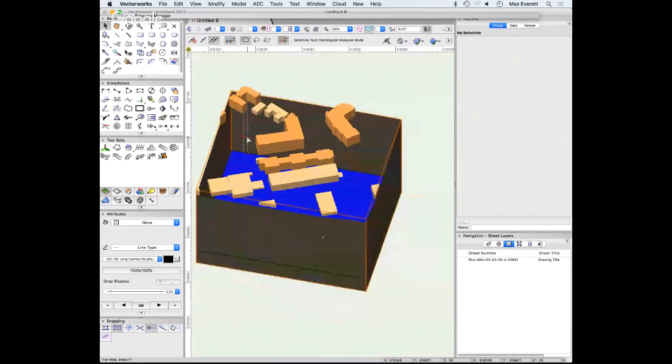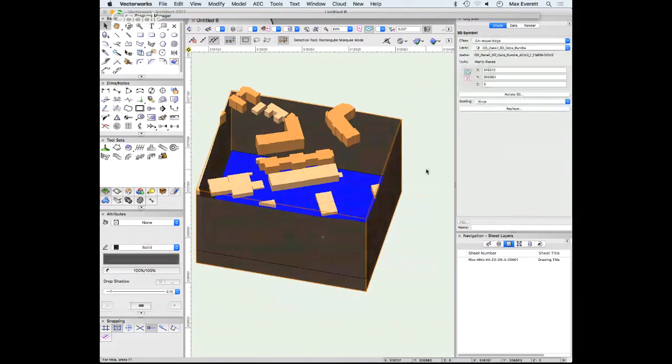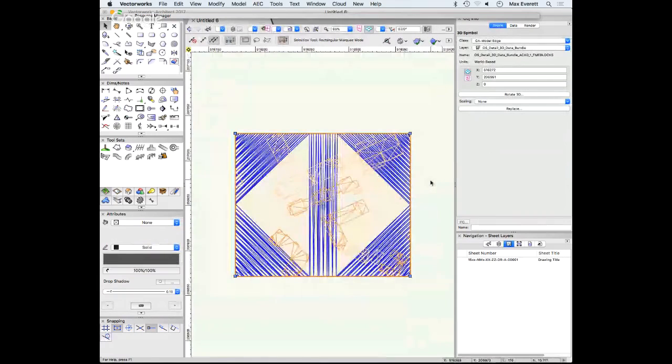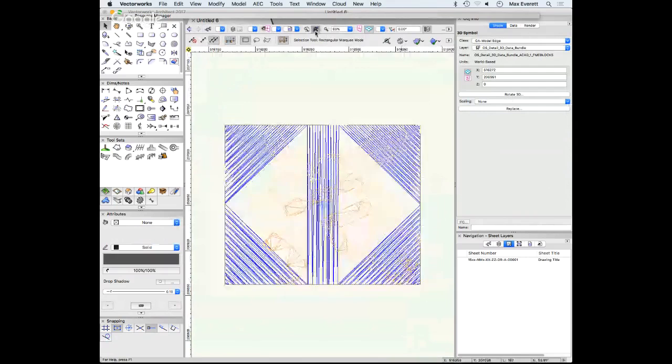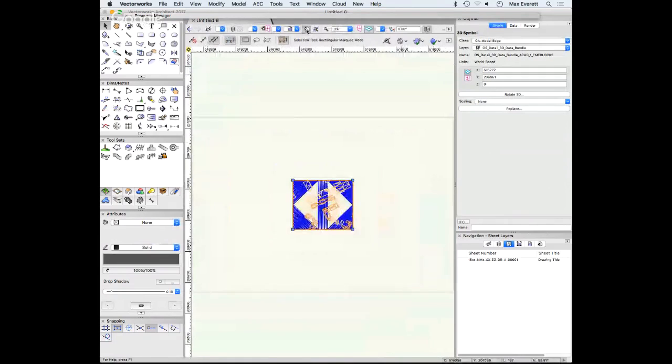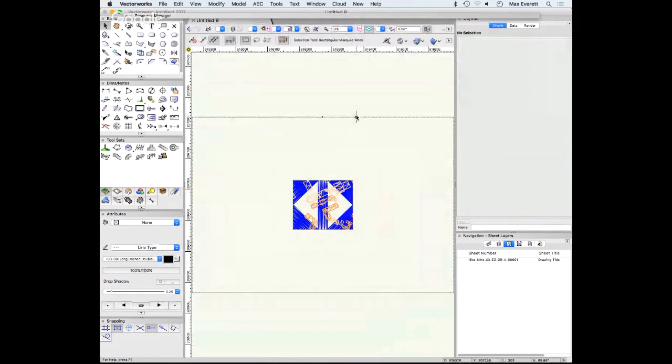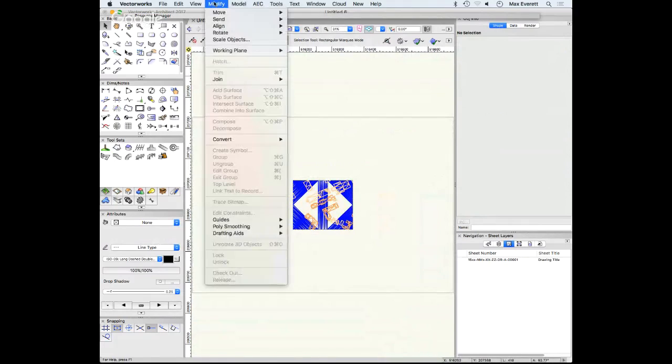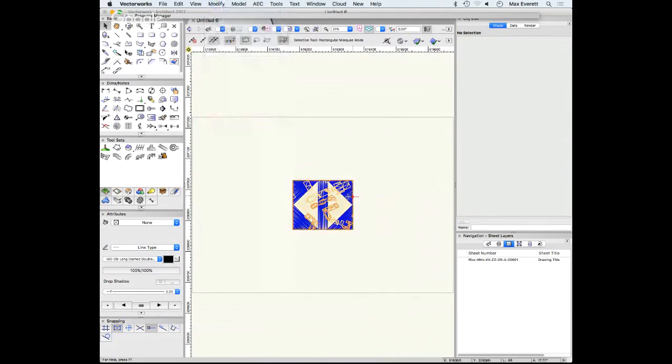There's something that I do with site models, where you right click on it and you can add a lot more data in. For example, this site model has quite a steep slope between the two sides, but if you wanted more accurate information, I use the site survey data, which has some spot heights on, and you can edit it by adding those in. So you just right click on the site itself.